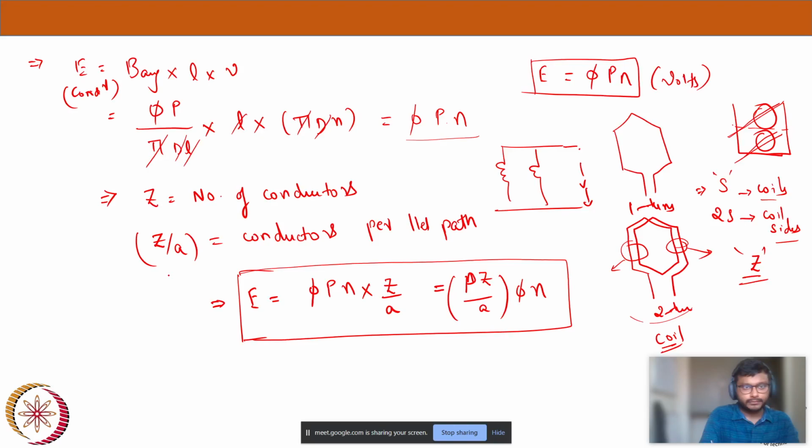To know the force direction, we need to use the left hand rule. Everybody take your left hand. My thumb will give the direction of force. So what will these two fingers do? My index finger is the field direction, and my middle finger is the current direction. If I know the field and the current, I can calculate the direction of force.